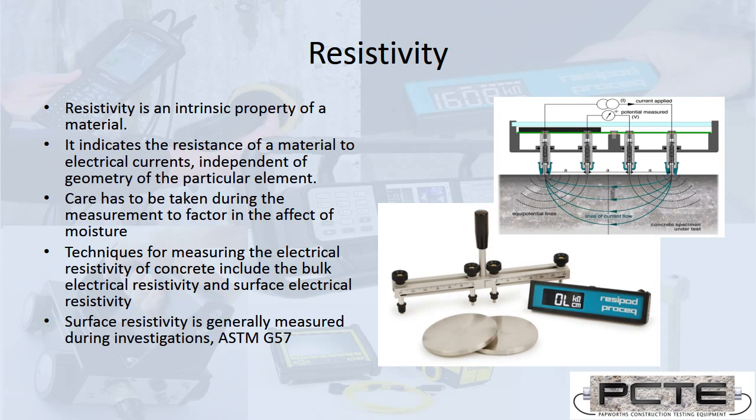Now, it's very important that the surface resistance and the internal resistance of the concrete gets taken into account. In some cases, it might be specified as part of work you do to use a drilled-in method, or it might be that a surface measurement is useful. It's all to do with making sure that there's no additional sources of error because so many things affect the resistivity. If you have the water content, the level of moisture in the air will also affect the measurements.